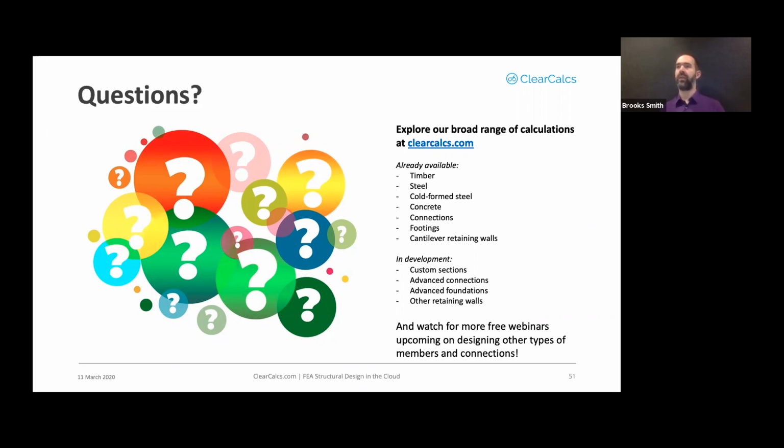webinar. Yeah, there is a minimum eccentricity recommended just to account for people hanging something heavy on the wall or construction being not exactly 100% 90 degree or slight flaws such as that. As far as other eccentricities, obviously just whatever is physically designed for.